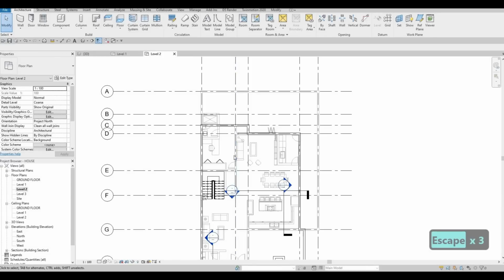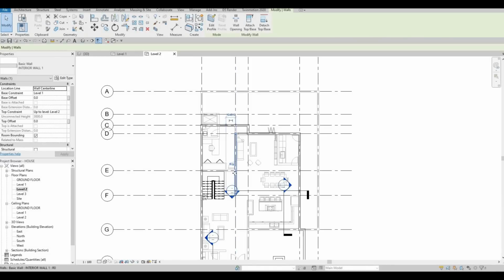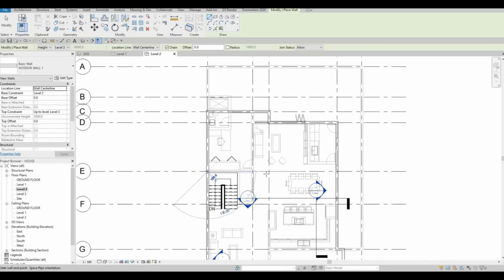Now we're gonna select our interior wall from the underlay base level, CS on that again. But right now, we're gonna start off at E1, and we're gonna create this wall right here, going to E3, and then closing it off right here. So that's one of the rooms right there. And then here, we can start off going right here in the midpoint.